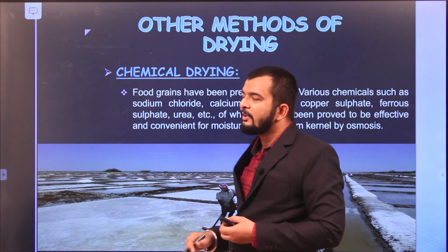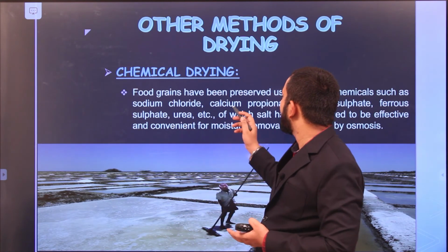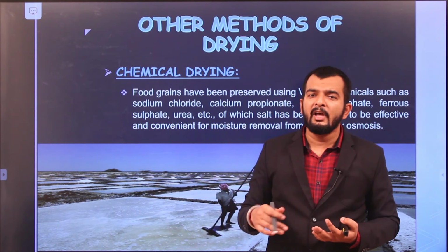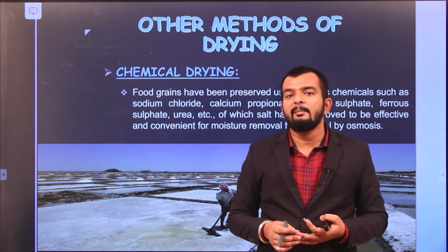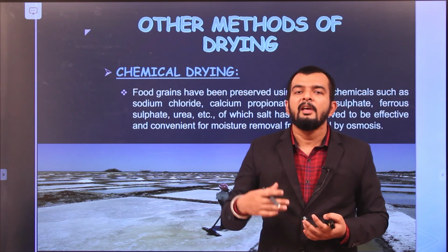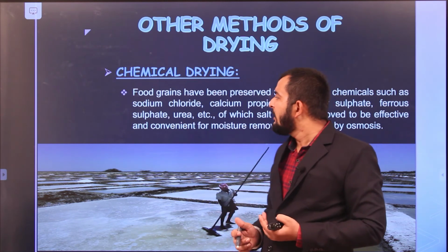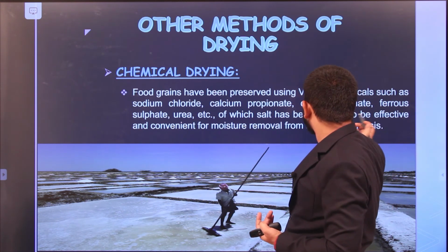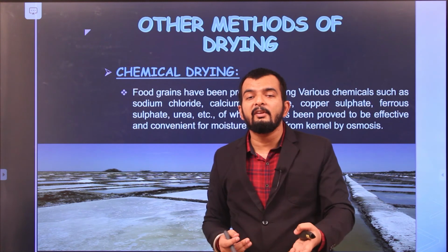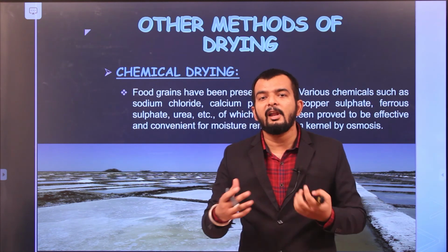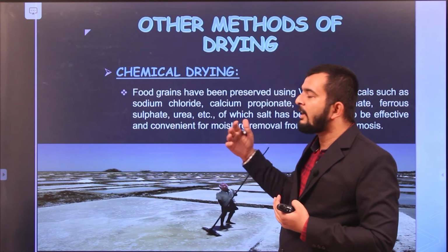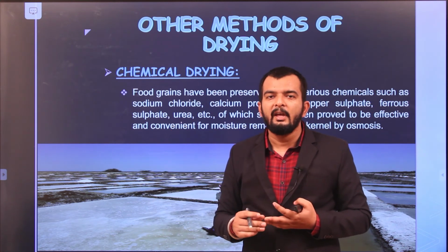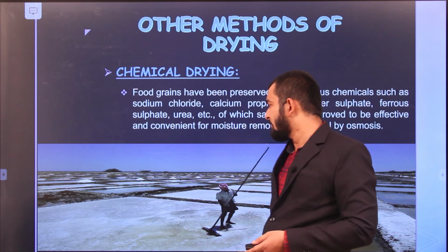So salt is mixed with your grains, or any other chemical which is inert and non-toxic for consumption, because if we are using this chemical method, some traces of these chemicals will remain in our food, right? So it should be inert and non-toxic. Since they are hygroscopic, they will absorb the moisture from the grains and will absorb it themselves, and drying of those grains will occur. The moisture content in those grains will decrease and hence shelf life will increase.